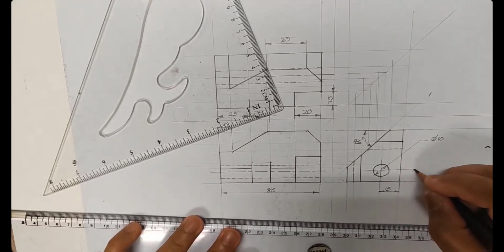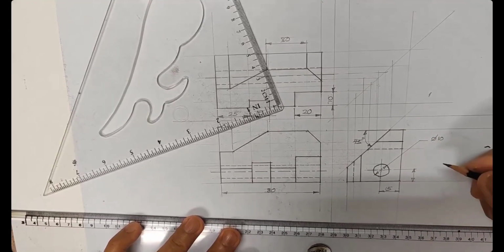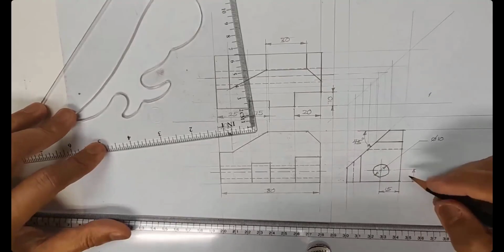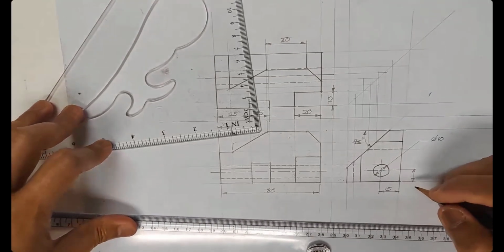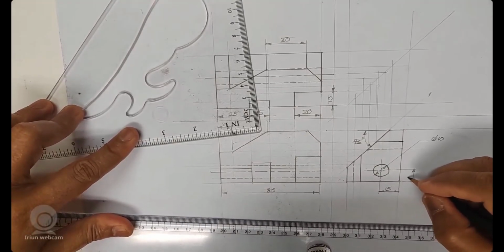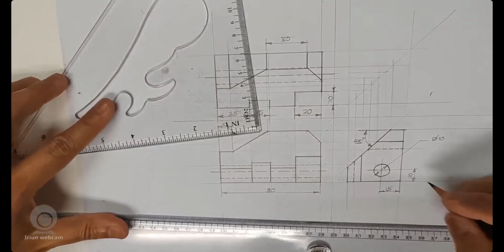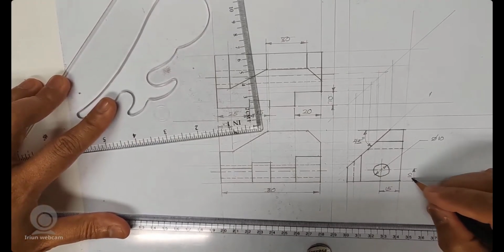So this will be your dimension line. Arrowhead, you can make it inward or outward. If too small, make it point inward, like this one inward. And here you write it vertical, as read from the right. You understand me, class? Then like this. It is solid, guys. I just show you this.